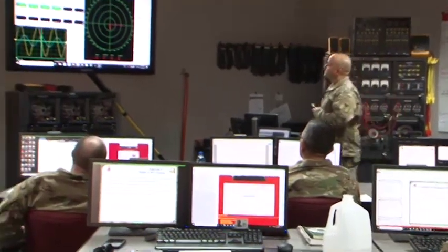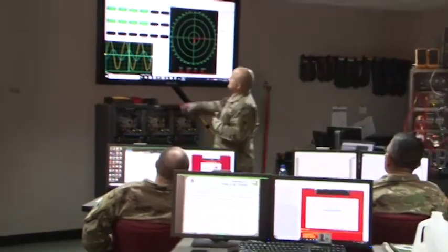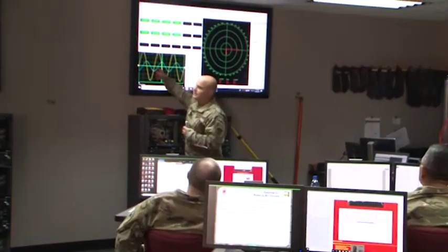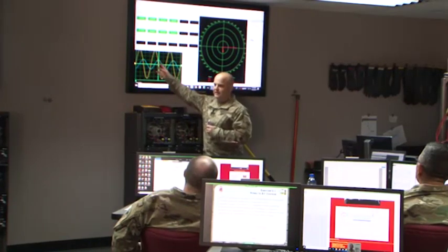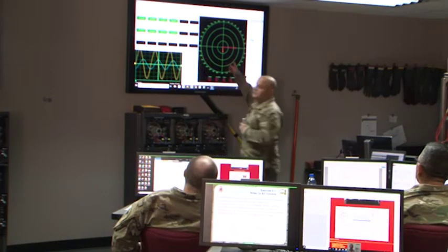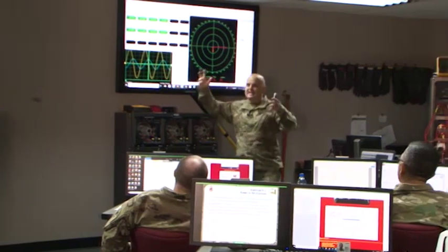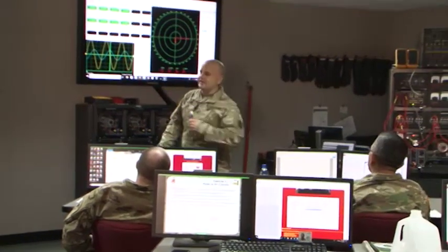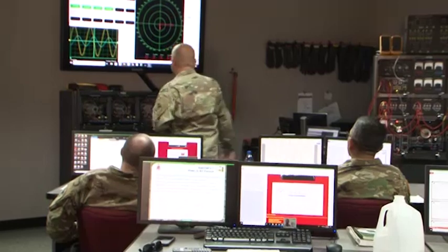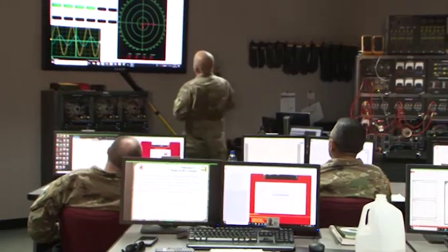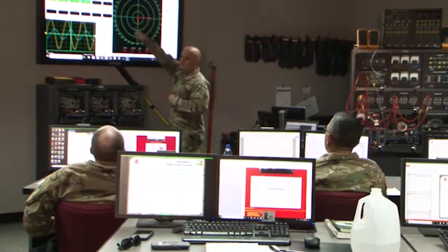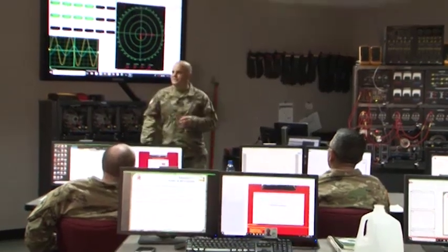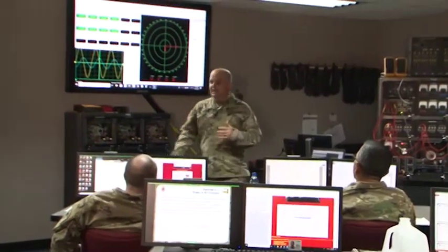What we're seeing now with these vectors is, it's hard to look at this, and I mean, you could do the time-based thing here and multiply times 360 and divide by the period. That's kind of complex, right? It's a lot easier to look over here and understand that 85, 86 degree offset of the inductor right there. Yeah? Yep. Okay, so now, this is my voltage vector. This is my current vector, and we said voltage is leading the current, right? That's ELI of ELI the ICE man.